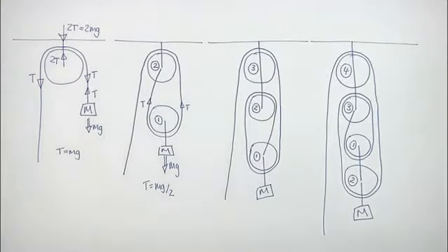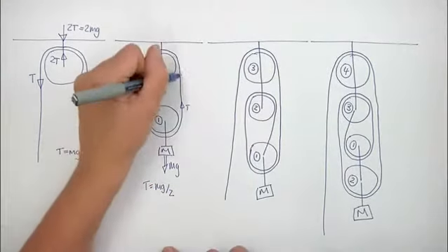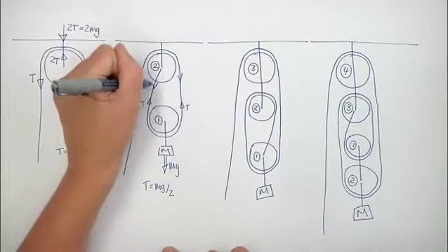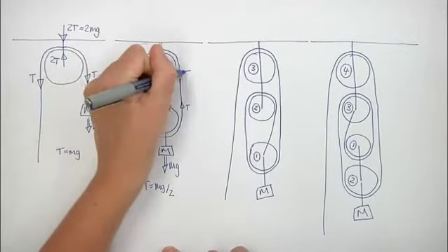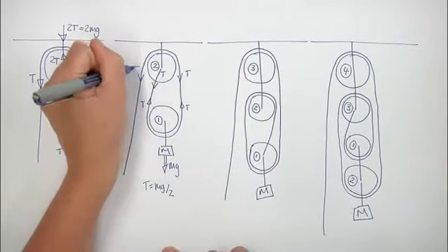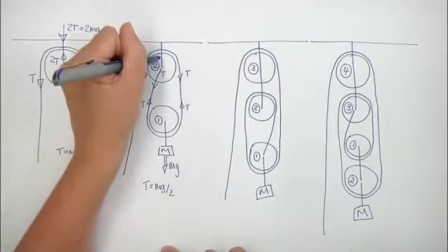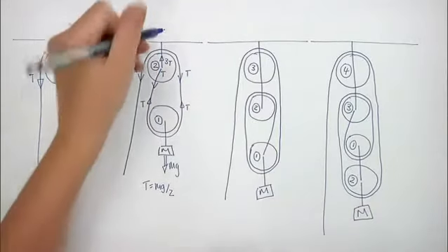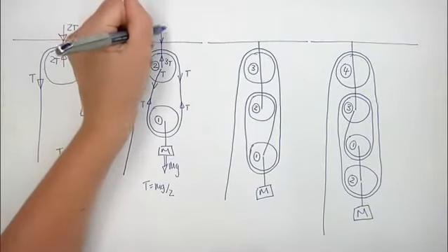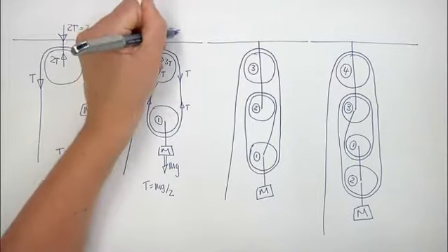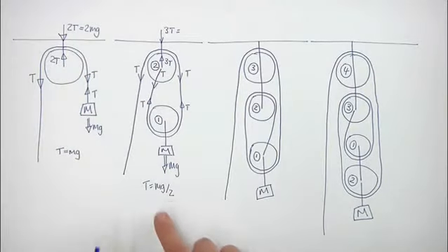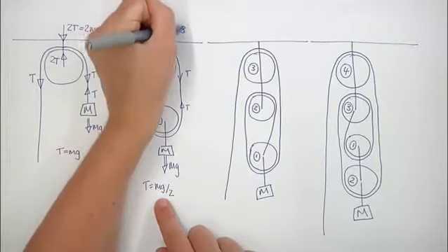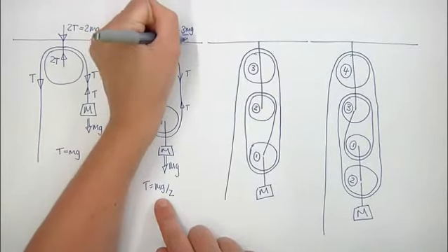Now let's consider the forces acting on pulley 2. There's tension T acting down on it in 3 places. So that means the upwards force on it must be 3T provided by the ceiling. So the force on the ceiling is 3T. And that's equal to 3mg over 2.